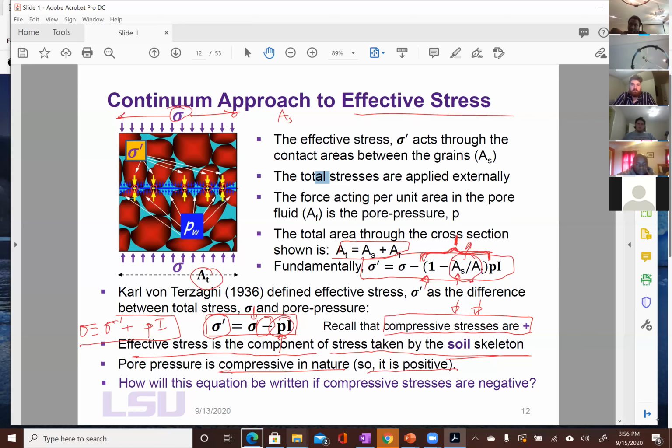And you know, nobody talks about pressure being minus 5,000 PSI. Whether you are working with engineering convention or oil and gas convention, we will still treat pressure as a positive value. And so the sign in front of it has to change to be coherent with the definition of the effective stress. And that's the question I'm asking here.